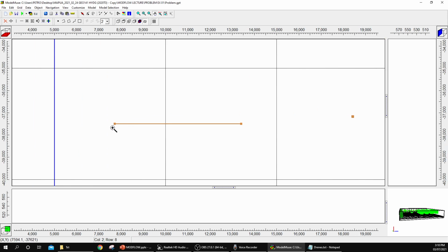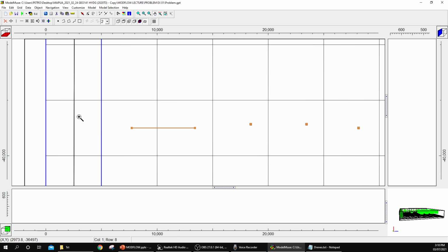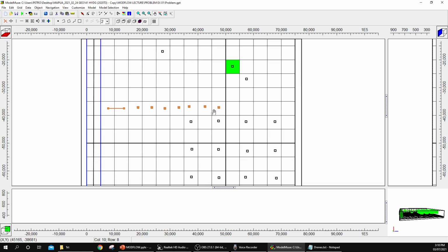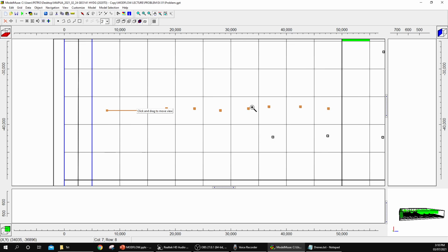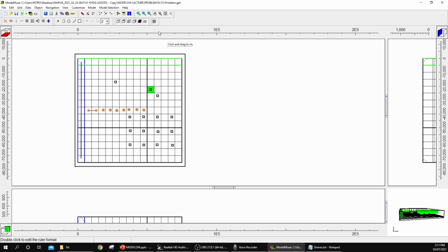It ends up here, and the next cell is basically just your outflow boundary. So the water is going from all over the model, draining out to your drainage holes, and it ultimately goes to this drainage channel, and this drainage channel will just channel out the water to your outflow boundary. So I hope that makes sense to you.